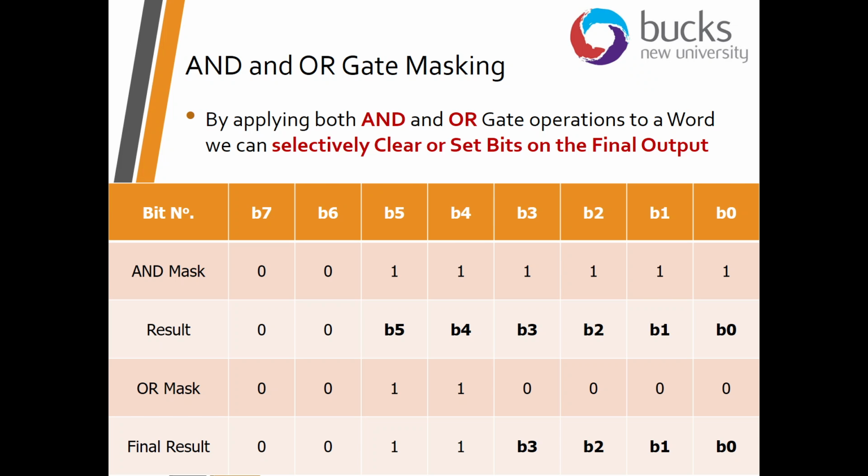So we end up with a pattern of bits in the last 4 bits as 1 1 0 0, and the first 4 bits as whatever the original word was. Now again, you need to understand the operation. Don't worry too much about the application at this point, but you must understand that this allows us to manipulate bits at the bit level by doing logical operations and an OR masking process to do those transformations, and that's what is really important at this point.